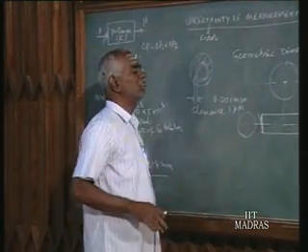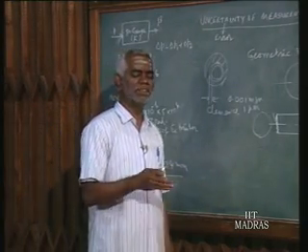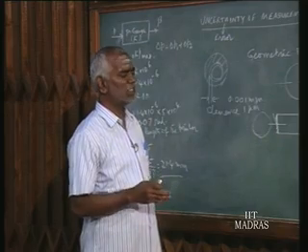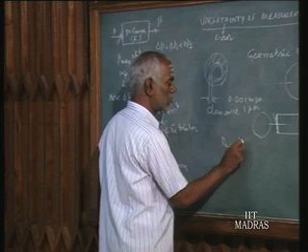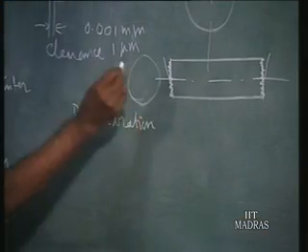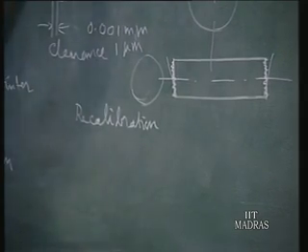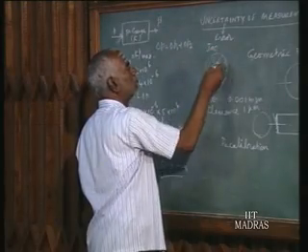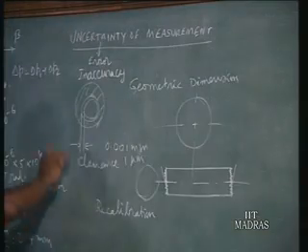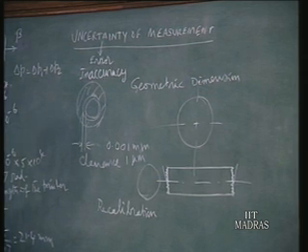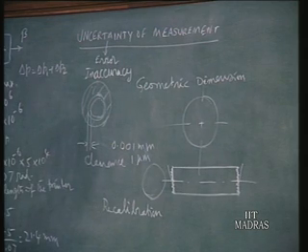Now another point is, after using an instrument for a number of years, the calibration of the instrument might have shifted. So after a few years of usage, that instrument requires recalibration to update the accuracy. Uncertainty, error, or inaccuracy are all analogous terms representing the same phenomenon. So we have to recalibrate the instrument, to check whether the error or uncertainty the manufacturer claims is still valid today.